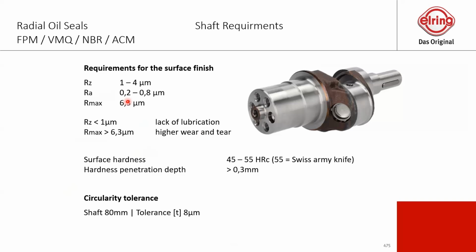If you overhaul or grind the shaft, then you will take this hardness away. This is a special thing, so maybe you also have to check the shafts and the conrods, what is necessary to fulfill, or if there are any special induction hardnesses on the surfaces. This is really something you have to check before you grind any surfaces of the shaft.